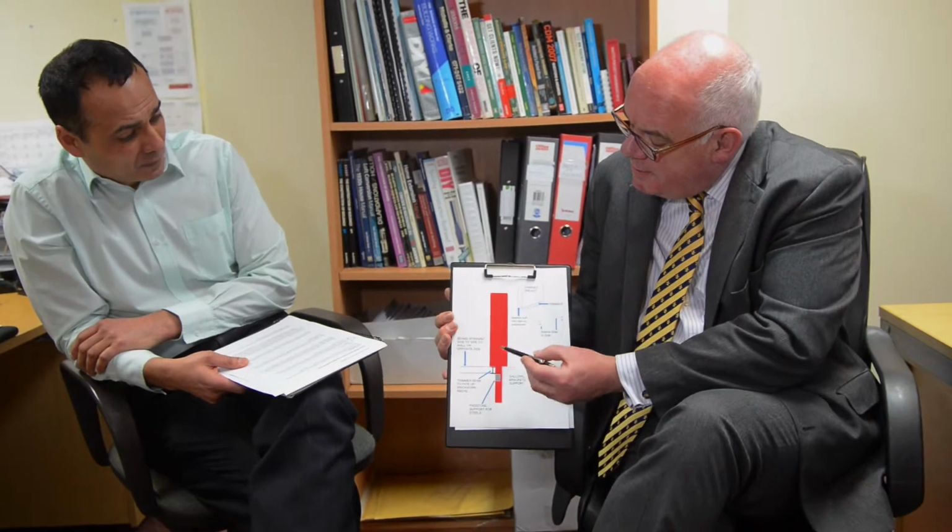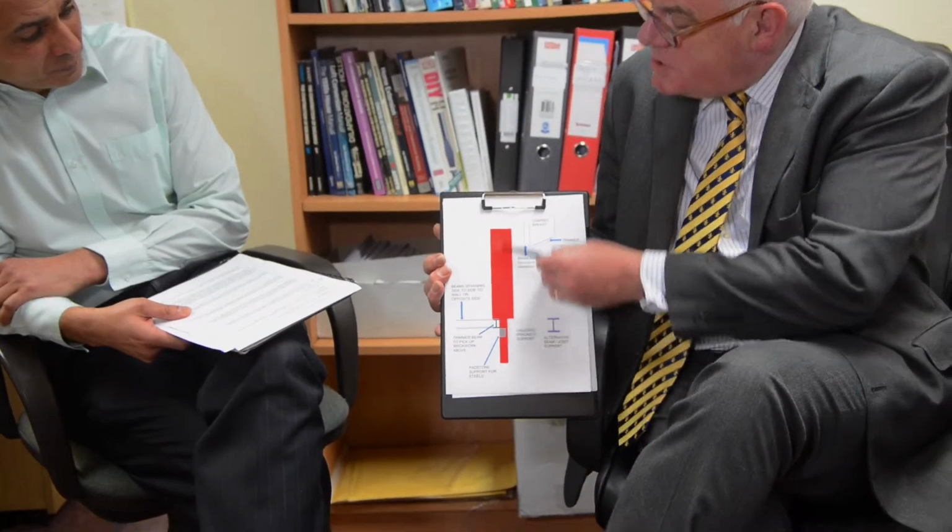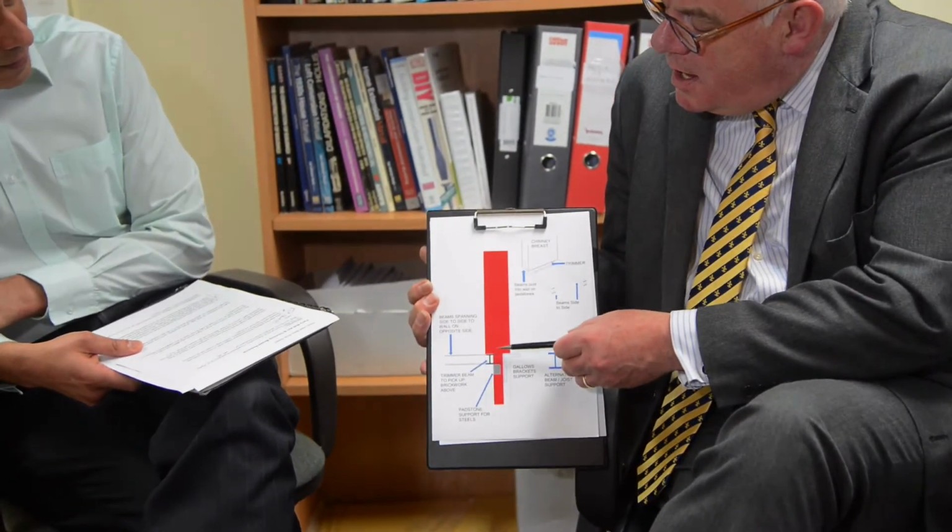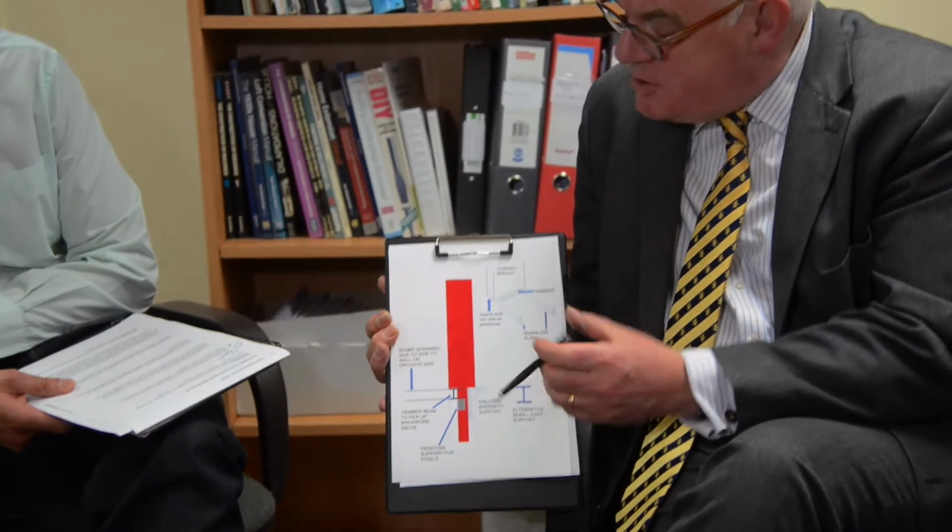So the neighbour has already removed their chimney breast on their side of the party structure. What sort of considerations do they need to have in place? Now, your building owner is in a slightly trickier position, in that he needs to provide significant support to this chimney stack to avoid the risk of it toppling over.